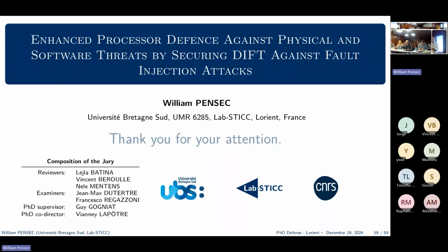Yeah, for table 4.1, I only did a comparison between the main methods of fault injection campaigns: formal method, simulation and actual fault injection attacks. I did not do a specific evaluation on different tools because there are a lot of tools, but mainly what I can say is, for example, formal methods tools are difficult to use for large designs, for very big designs, and it will take a lot of time to simulate. There is also some limitation with formal methods due to, for example, design complexity. If there are some loops inside the design, there can be some issues with that.